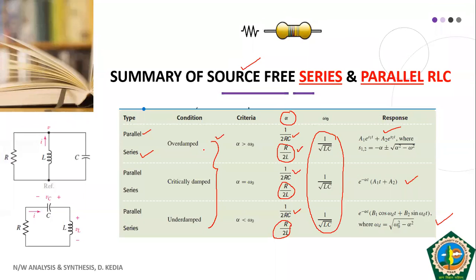In both the cases, we have not assumed any independent voltage source or current source present in the circuit. We have seen the natural response of this circuit. And dear students, now we need not consider the forced response separately. The concept of forced response we have already seen in case of RC and RL circuit. So if we want the complete response, we have to simply add the natural response with the forced response. And the concepts of calculating forced response in case of inductor and capacitor, we have already seen. So the same condition will apply here.